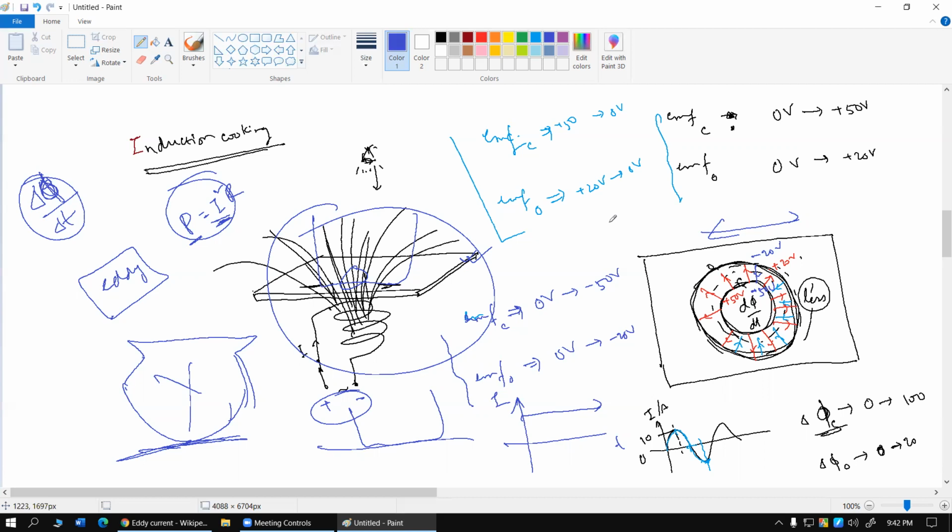different parts of a conductor are subjected to magnetic flux linkage at different rates, thus producing an EMF within itself in different locations. So one part of the location would be having one type of EMF, the other part of the location has the opposite type of EMF. So there would be a current flowing through the conductor internally, and that internal current is what we're defining as the eddy current. So what do we have to have for eddy current? Different parts of a conductor piece should be subjected to different rates of change of magnetic flux.